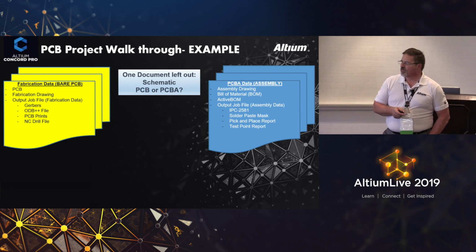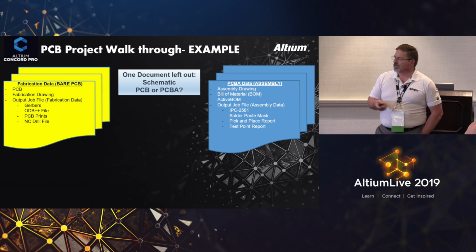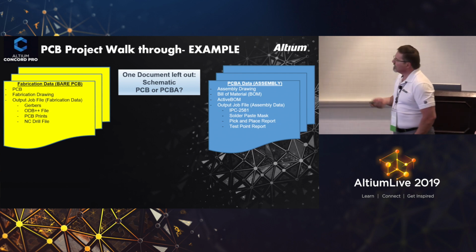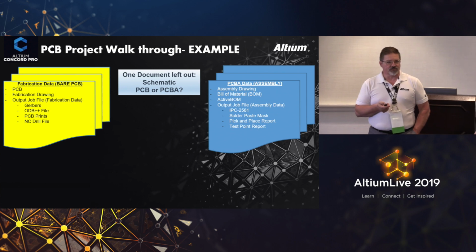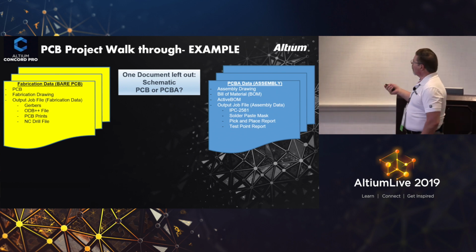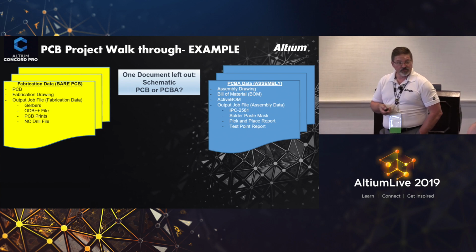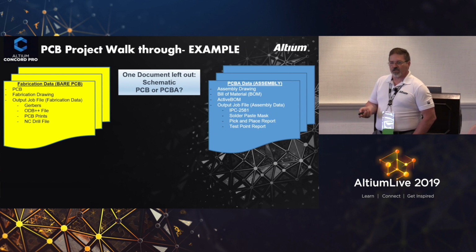I mean, that's what you use to troubleshoot a board, right? If it's not working, so. All right. But also keep in mind about child-parent documents, okay? Your schematic changes, your PCBs don't. If you have a variant change, if you have a do not install component or an alternate component, then that changes your BOM.